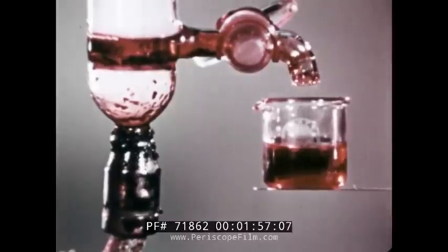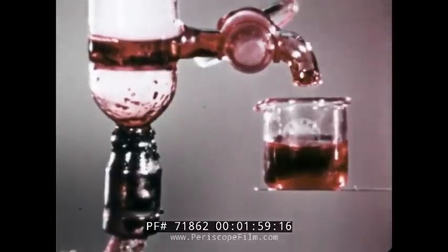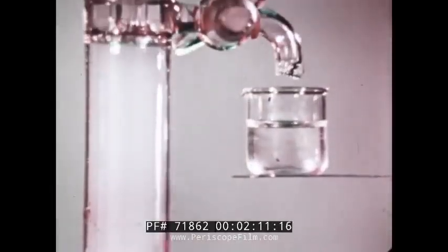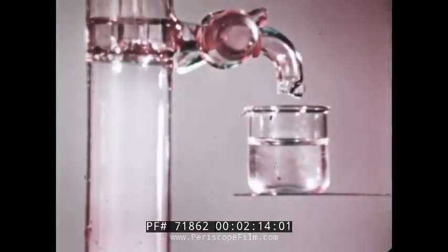Near the bottom, the vapors are cooled to just below the boiling point of the dark liquid. So it condenses here and can be drawn off. But it's far too hot for the vapor of the clear liquid to condense. So it rises until it too is cooled sufficiently to condense. At the top of the column, clear liquid is collected, and at the bottom, dark liquid. The clear liquid will contain a small amount of the dark, and vice versa. But these amounts are slight because their boiling points are far apart.